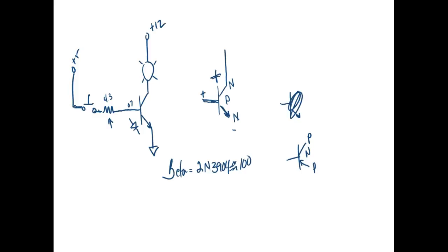But, you know, so if I'm getting 100 milliamps up here, then we would have 1 milliamp going that way. Down here we'd have 101 milliamps. Up here we would have 100 milliamps because we have 1 milliamp worth of base current. Does that make sense? So for all practical purposes, we say that the emitter current and collector current are equal. And these guys right here, so look. So let's come over here and do this.